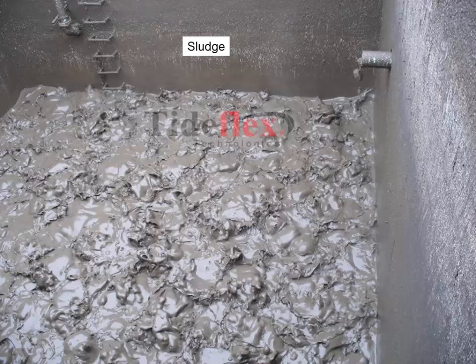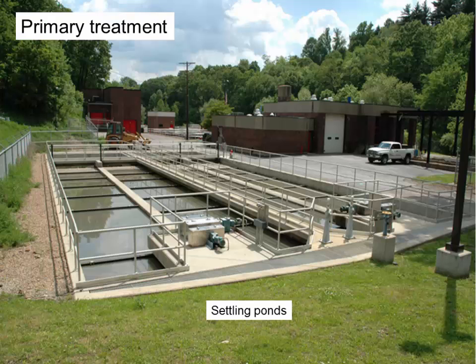Up to 1972, this was the end of the road. This was clean water. Before the Clean Water Act, and still in developing countries, this is the way they clean their water. Just settling things out. Now, if you're following along and if you're thinking ahead, this primary treatment does a great job of settling out solids. It does a great job of floating the greases and oils to the top. The middle of the water is clearer and cleaner, but it is not free of bacteria.